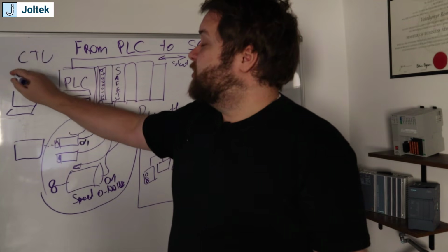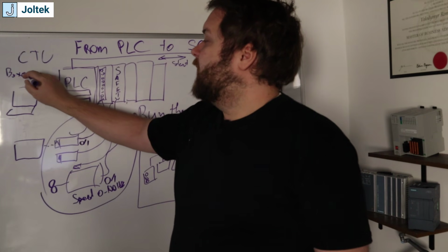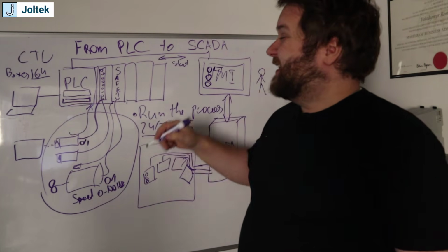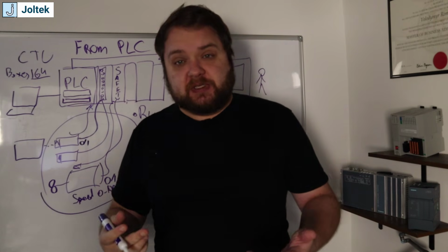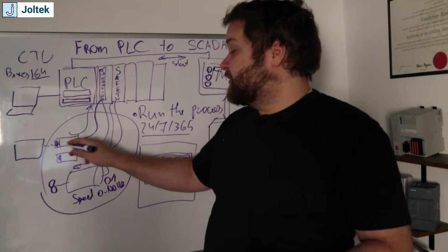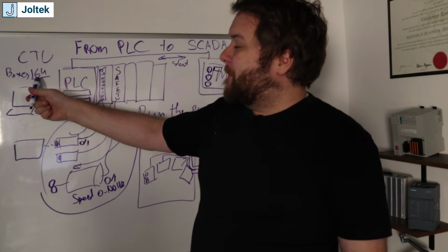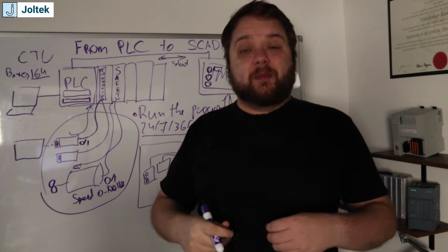And so this is going to become boxes, and this becomes a counter, right? So let's say it's like 164 at this time. This is data that is generated by the PLC. The only thing that is raw information is going to be this sensor that's going to trigger from 0 to 1. But in this case, we need to combine the counting principle, but we also may want to combine the time,